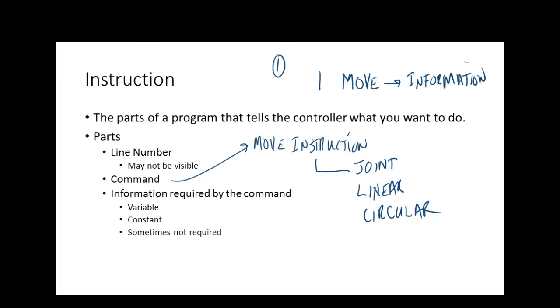Well, not axis, because now what we're doing is moving the robot. When we jog the robot, we have what we call a joint jog. Don't get the joint jog and the joint move confused with each other. They're not the same. With a jog, I'm coming up here and pressing buttons. When I tell the robot to do a joint move, the robot's going to move, and the controller determines what axis it needs to move to get that thing to the position that we told it to get to.